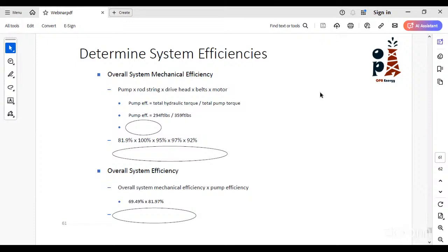Another example, if you are running your PCP in a very deviated well or a well with a higher dogleg severity, what consideration should you have? As we all know, this rotational motion can cause fatigue stress on the body of the rods themselves, or even fatigue stresses on the tubing and make cracks with time. So you can deploy many guides on the rods in the deviated section, or even the high dogleg severity section. You can deploy molded rod guides on your rods, and you can get benefit from them.